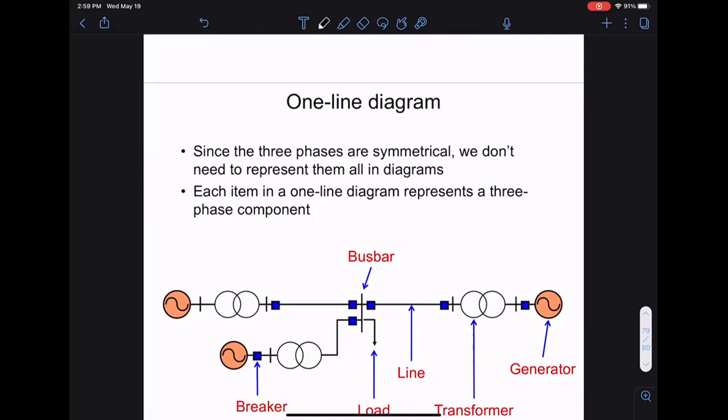So how do you do that balancing? Each of you has a single phase load, but from my utility to the transmission grid, I want to look like a balanced 3-phase load, right? Because the whole thing is designed around being balanced. So how do we do that? Get different groups of houses to be on different phases, so it roughly balances in aggregate. But how do we make sure it's balanced in real time, so you don't get unlucky and have one group of people not home in one area?